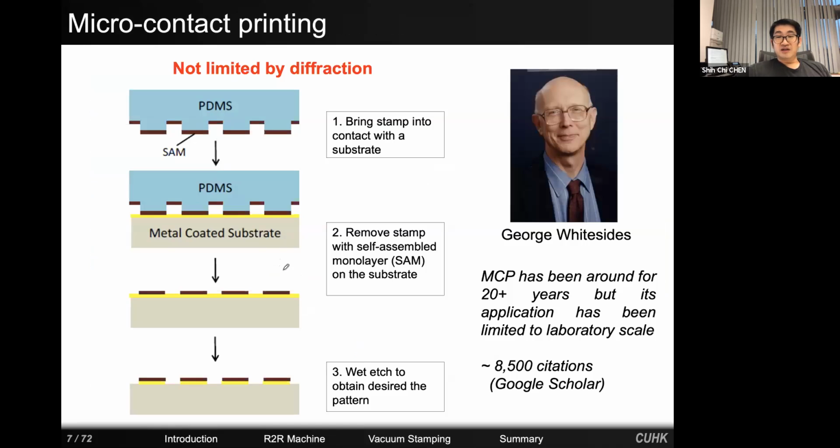So we talked about micro contact printing in the earlier slides. Essentially, you start with a PDMS membrane, and you ink it with molecular ink, which is SAMs, or self-assembled monolayers, or thiols. Once that ink is properly dried, you can transfer the ink to a metal layer like gold, forming a SAM layer, and then followed by etching. So that's the basic procedure that we talked about.